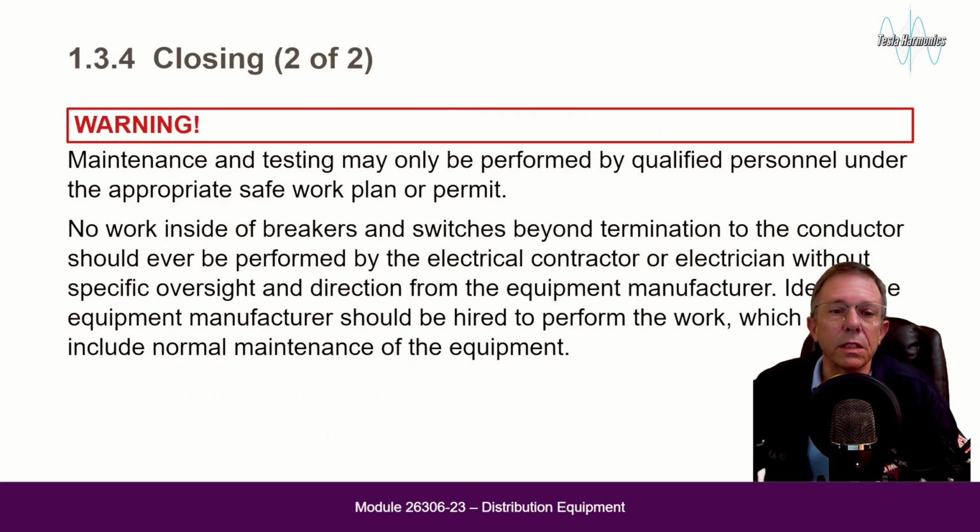Warning: maintenance and testing may only be performed by qualified personnel under the appropriate safe work plan or permit. No work inside of breakers and switches beyond termination to the conductor should ever be performed by the electrical contractor or electrician without specific oversight and direction from the equipment manufacturer. Ideally, the equipment manufacturer should be hired to perform the work, which may include normal maintenance of the equipment.